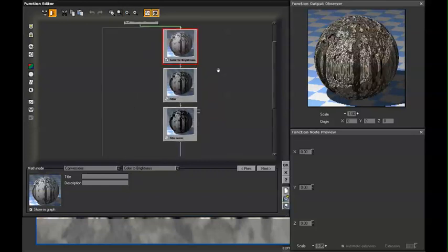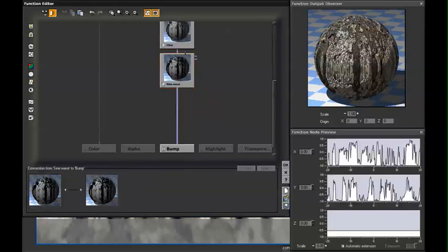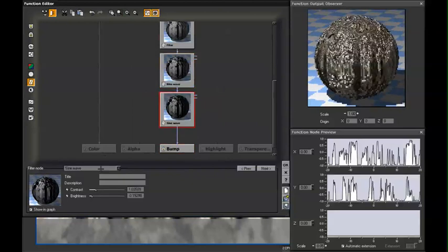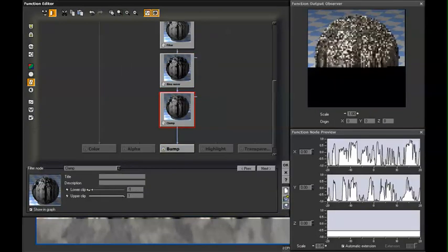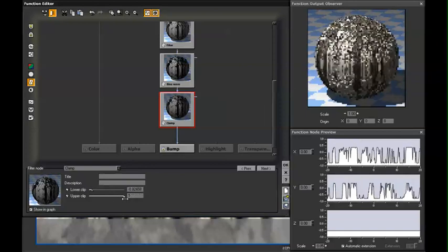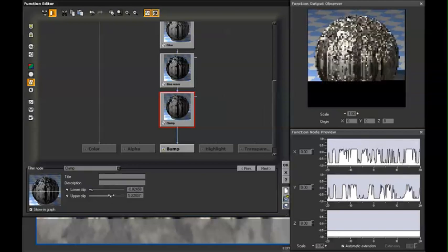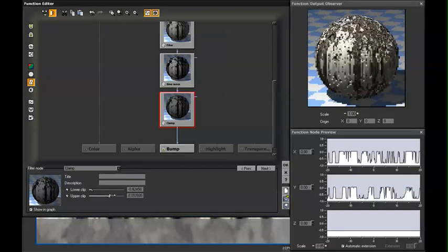And we're going to go down to the bottom, just before our output, add in another filter, and we could use the clamp mode, and we can set up our lower clipping, but mainly we want to adjust, in this case, the upper clipping, because we want it to be a little more uniform and not look so bad.